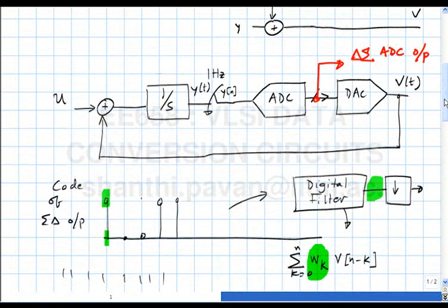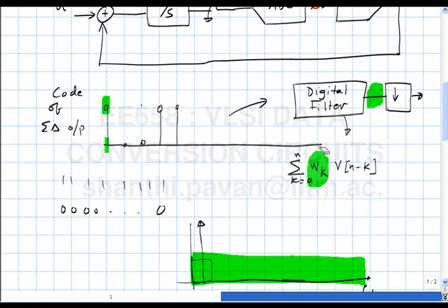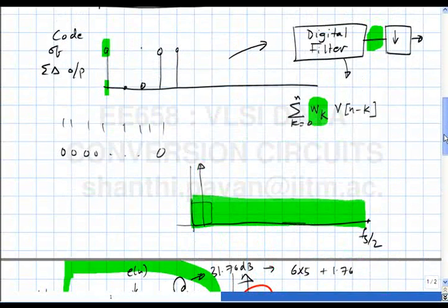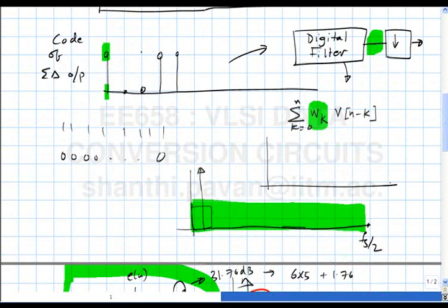Okay. So the oversampling A to D converter is doing better by simply, yes. Oh, okay, so the question is if you made WK a 32-bit precision number rather than a 16-bit precision number, are we going to get 32 bits out equivalently. The answer to the question is yes, provided the in-band quantization noise is smaller than that number, correct?